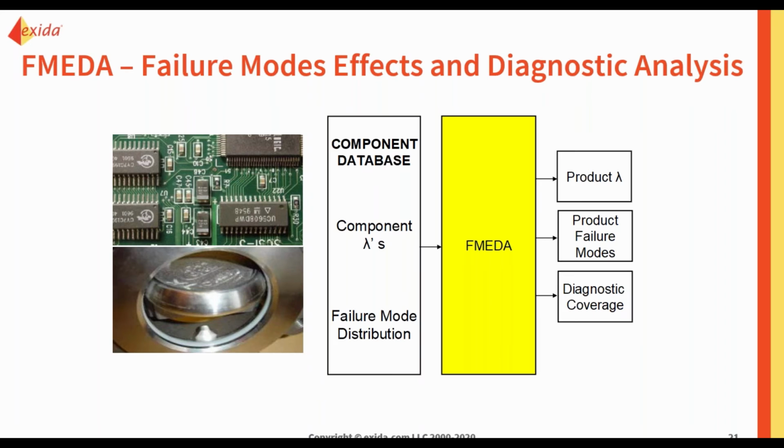So the FMEDA analysis is both application specific, environmental specific, and it considers how the device works, how it's set up, where it will be operating. So it's very specific to how the stresses will be applied. And that's how you can get those specific failure rates for the applications. You will have a different failure rate, maybe for close on trip, then tight shut off, then open on trip. Different failure rates for subsea versus offshore versus cabinet mounted. Different failure rates for clean service, severe service, dynamic or static application, along with all of the different environmental profiles.